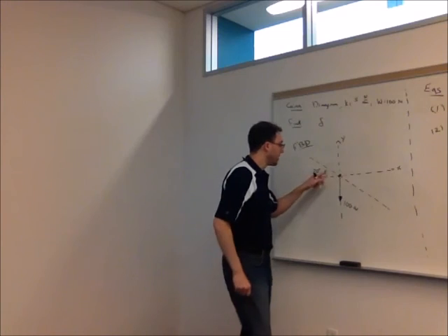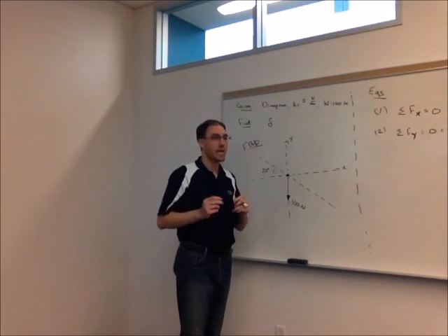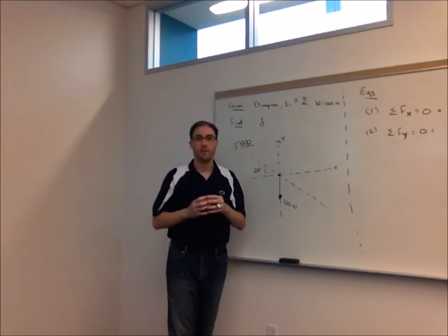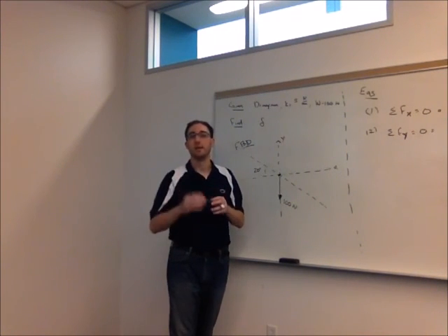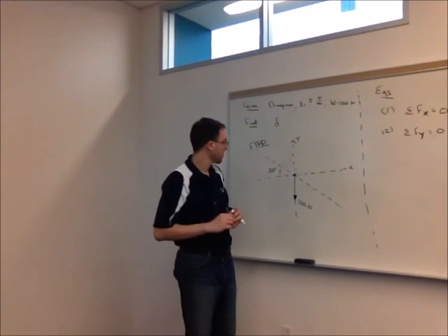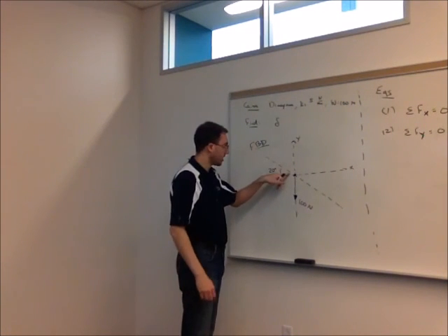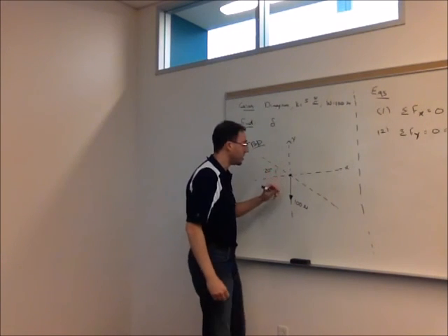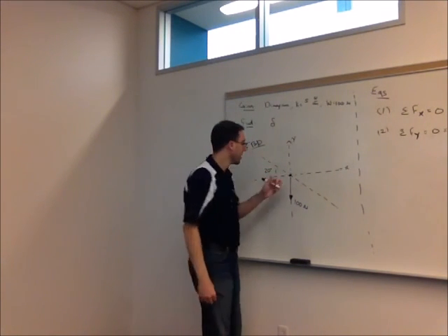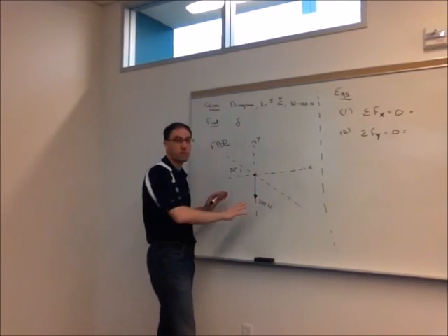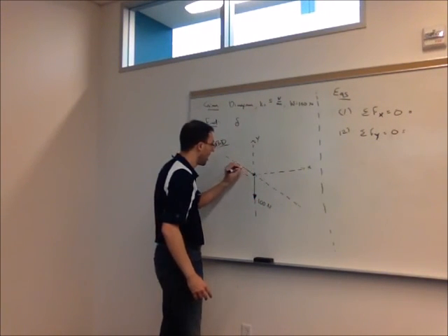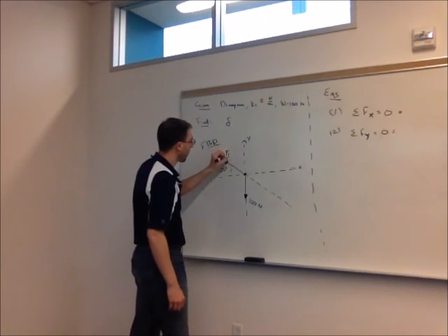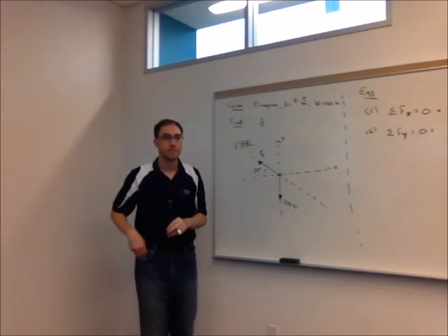Right, so a little bit more detail on that. There's going to be a force from the spring. What is the direction of this spring force? Up into the left. Right, so the way that the picture has it, it's along that 20-degree incline. I'm going to make the assumption of tension, because that's how the equations work. You could assume compression if you wanted to. But I'm going to assume it's in tension, so it's pulling on this crate. And I'm going to call the force in that spring F sub k.